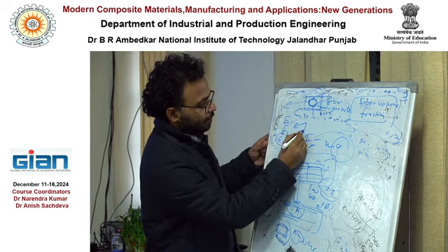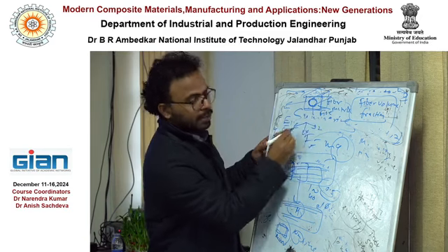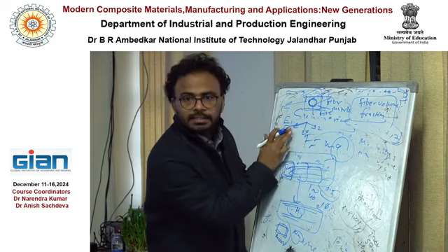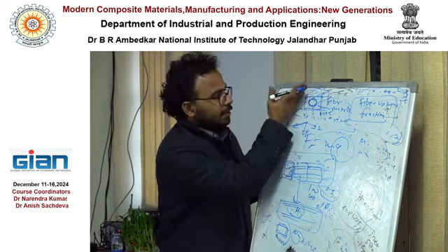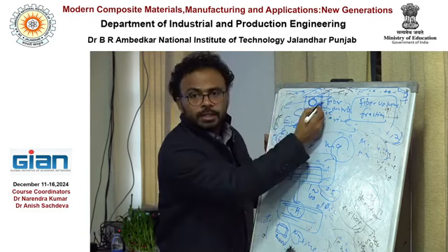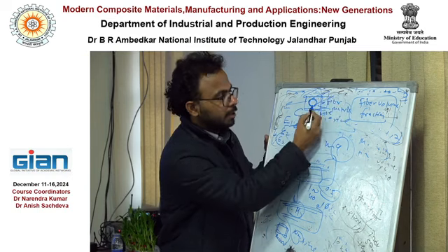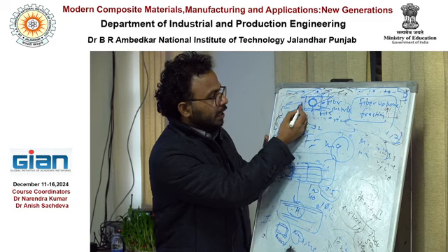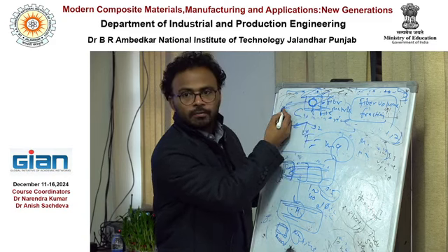X direction, Y direction, Z direction, right? So suppose you are applying the X direction load, make sure this is only the X direction deformation. This direction, this direction, this direction deformation 0. How will you make 0? Make the periodic boundary condition here, here, here, and here, right? Only load this will give the displacement of this.